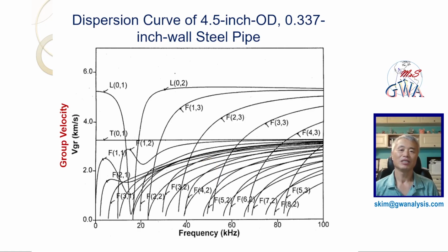For answering this question, we must remember what the purpose of guided wave testing is. It is finding defects. For finding defects, we need to transmit an ultrasonic wave having high spatial resolution with one cycle in the low-frequency ultrasonic wave testing. I'll explain it more in the following two slides.